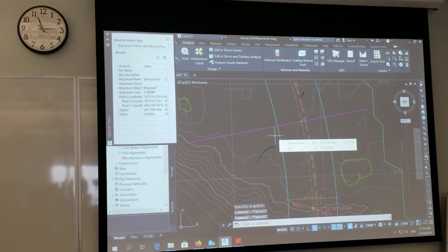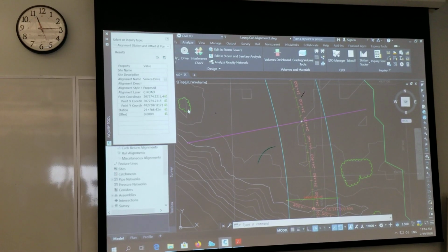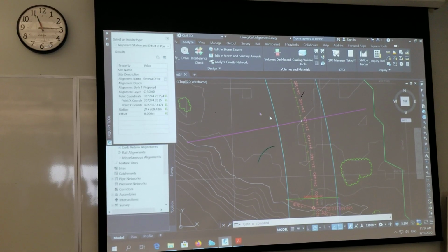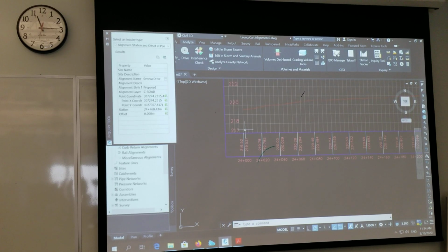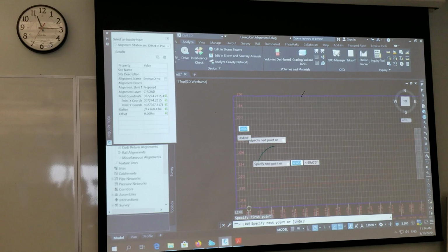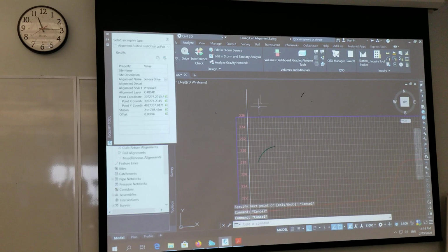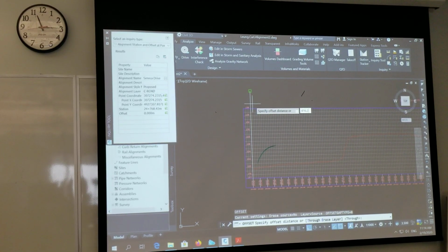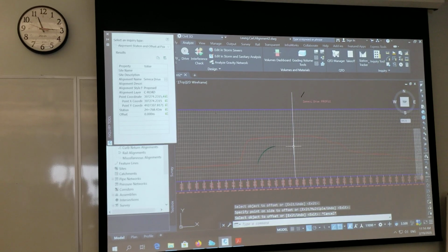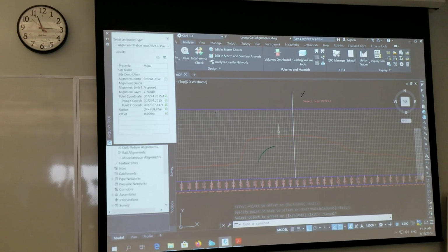Now guys, this is one method of doing it. I know that this point is here, and I know that this intersection over here should be 24,416.200, right? So I could easily come here and draw a line at 2400. Pay attention, don't do this yet, because I'll teach you a different, easier way. But see if you understand this. If I offset this line over here by 416.2, this line over here would follow exactly where the intersection is going to be. Do you guys agree with me? So here my railway is going to be.